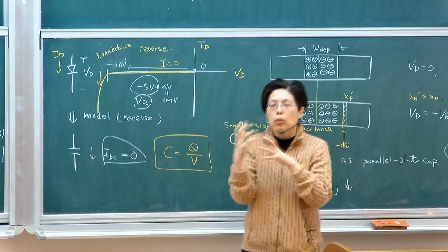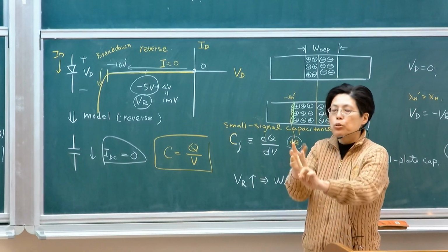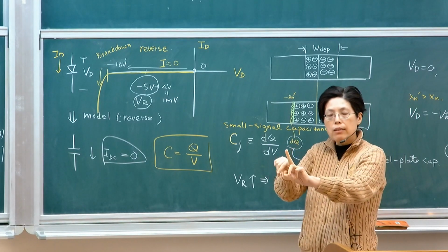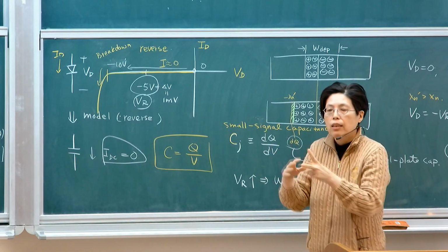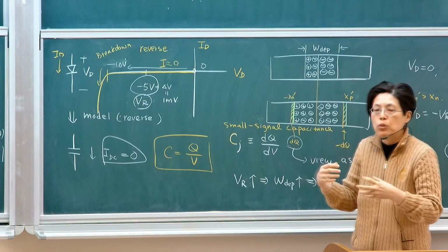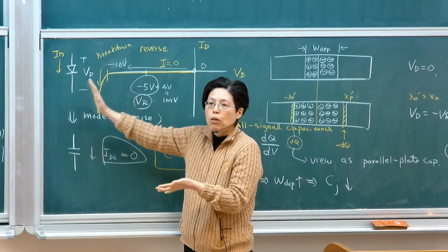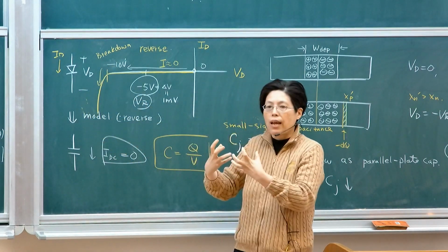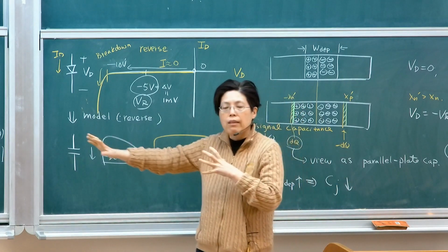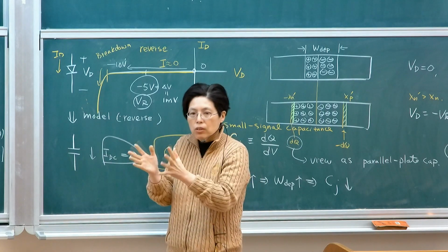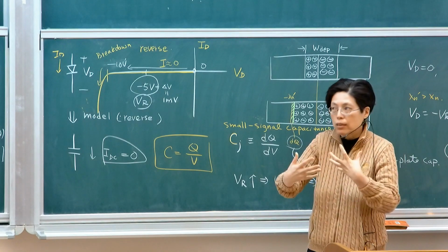We're going to talk about circuits a little bit later, but you will think about a diode in two modes. One is that when it's forward biased, it's typically conducting current, so you want to know how much it can conduct. When it's reverse biased, the main purpose is to shut it off. So when you shut off, you want to make sure that it does shut off under all conditions. It does not break down when the pressure is too large. So a good switch should turn on and provide high enough current when it turns on, and when it's shut off, it should be robust in order to endure high stresses.